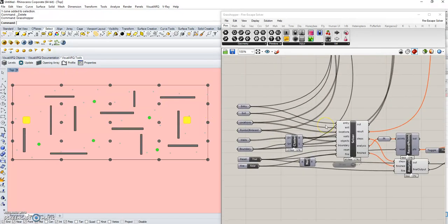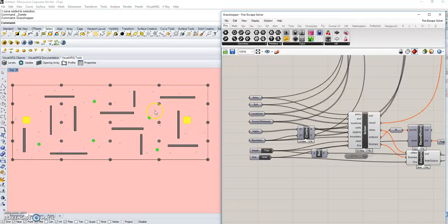To dive into my script and how it works, it is essentially an agent-based system which uses object-oriented programming and KD trees to simulate humans moving around in space in the case of fires. A few things that I've done is create an obstacle detection and collision algorithm that is true for humans. When you use typical Boid algorithms, they tend to stick to walls and go through walls. But when humans move around, they actually use the vertices of objects and move around them, especially if it's a fire and they want to get around an obstacle, for example.